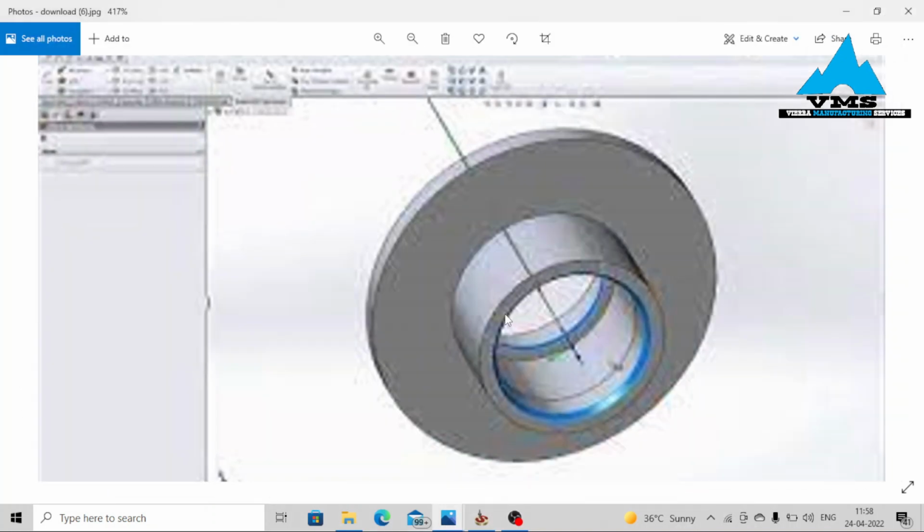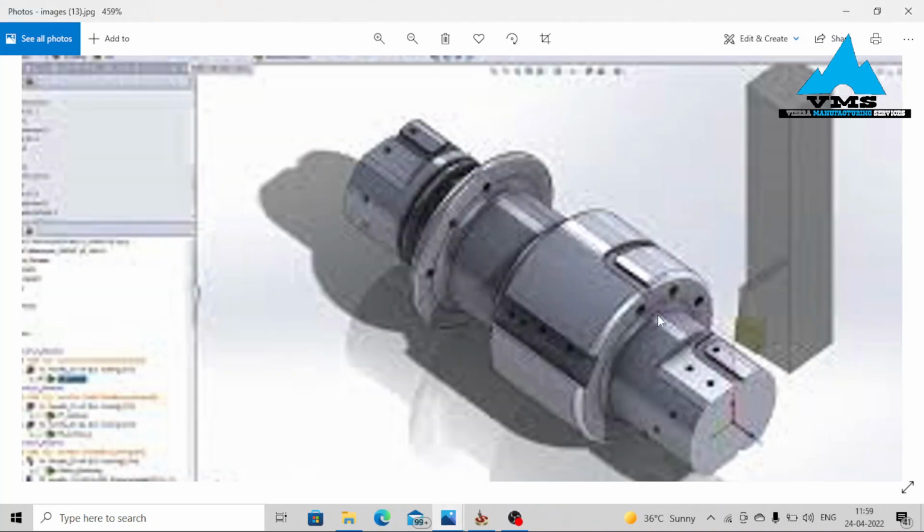Okay, good. If you divide this one, you notice that its center line falls around its symmetry line equally. So now we got just turning operations, no slot, no engraving, no milling operation at all. So this is a typical turning system. Looking at this fourth example, if I divide the part into half, we got some turning system. However, we got some holes at the surface, right? These holes at the surface cannot be mirror images of one another. So this clearly tells you that we have a combination of both turning system and milling system.